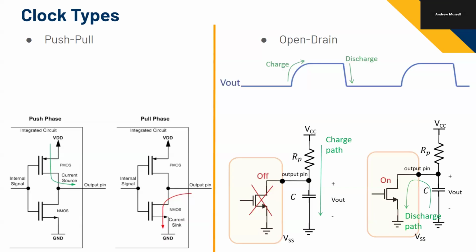In reality, MOSFETs have some leakage. So you are going to have a little bit of current going through here or through there. So that's something to think about. When MOSFETs are on, you can look at the RDS resistor. RDS is R for resistor between drain and source.